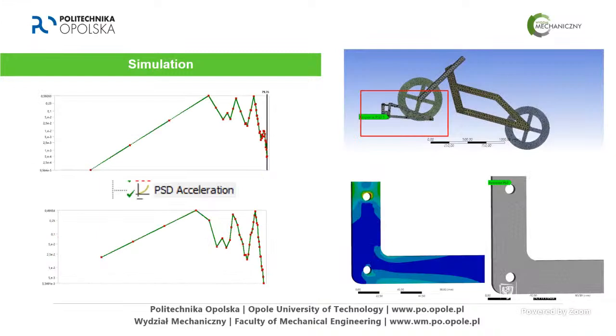And the next step is the simulation. We made it in ANSYS, where we can implement the PSD acceleration. But the first step is the static structural. We test the device and decide on which element we can do the next simulations, modal and fatigue life.